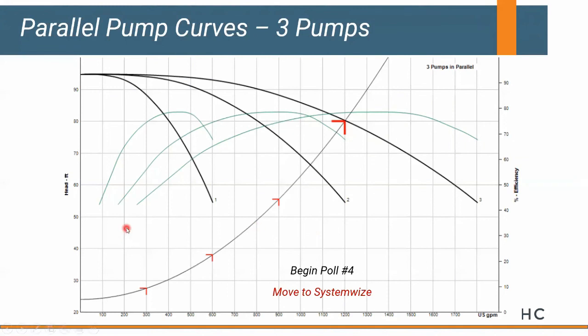No, Hans, that's a great point, and it all comes down to pump staging, best efficiency points, where you want to bring pump number 1 on. You might be able to run pump number 1 up to 40 hertz or so. If you picture variable speed curves tied on top of this, that's what Hans is talking about. Obviously, this system curve is going to fluctuate based on two-way valve operation out in the system.